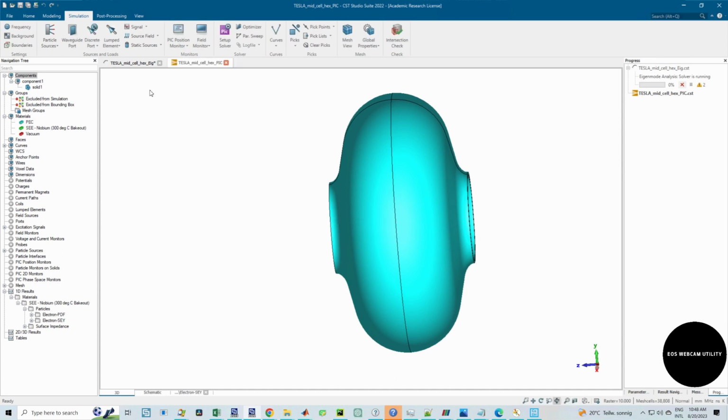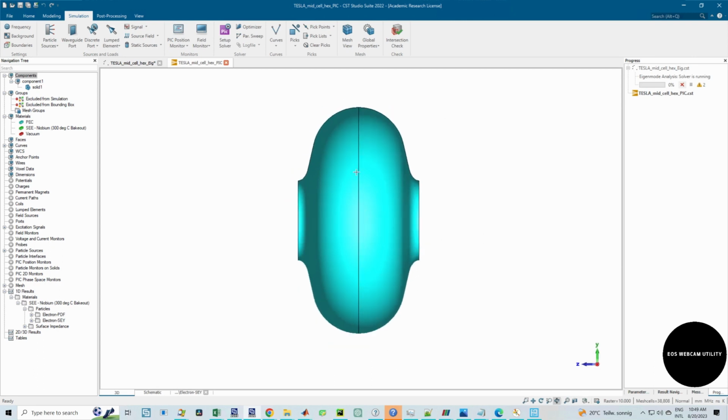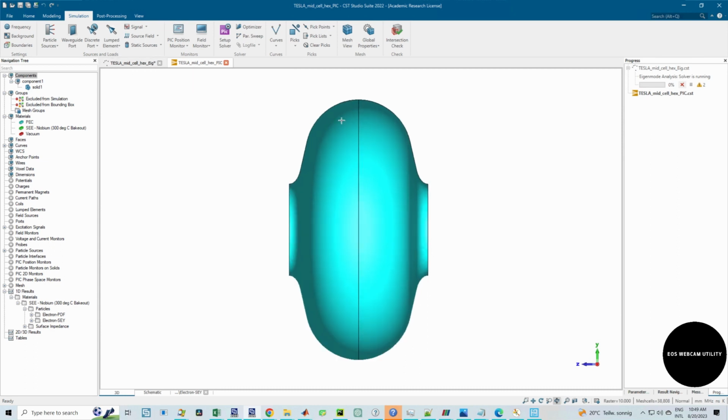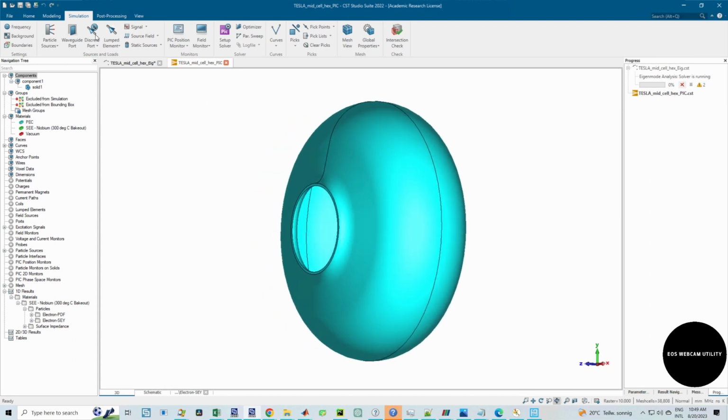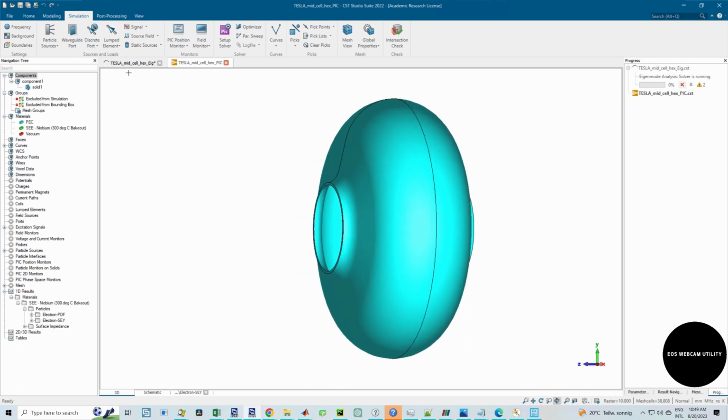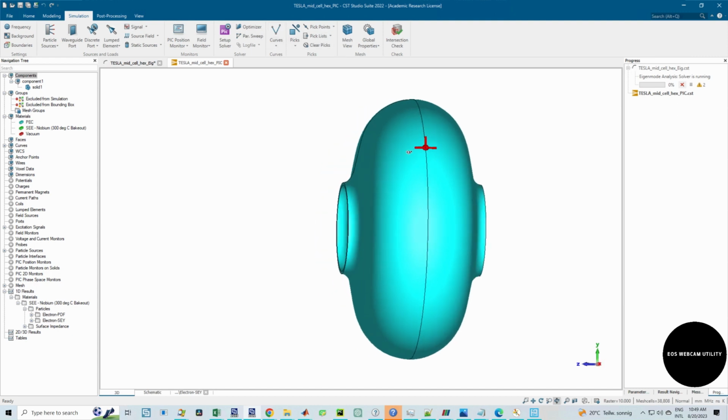Oh, and before I go, I'll just set the mesh properties now. You don't only need to have a fine mesh for the eigenmode simulation, but also for the PIC solver. Now I think I made a mistake. Before shelling, I should have refined also at the equator. But then let's look at the mesh.